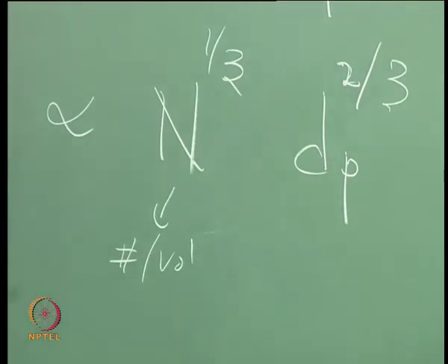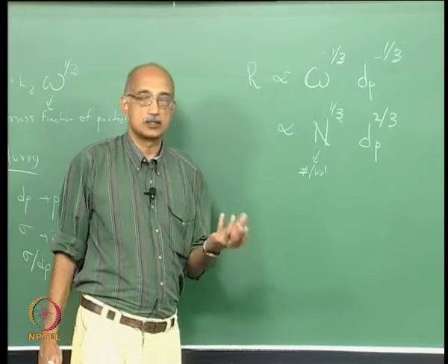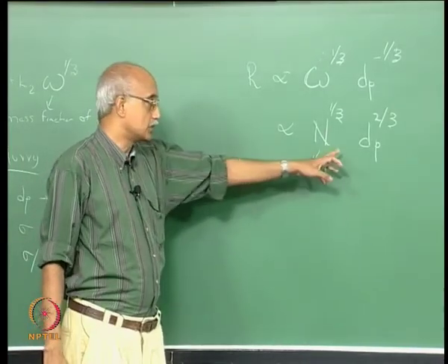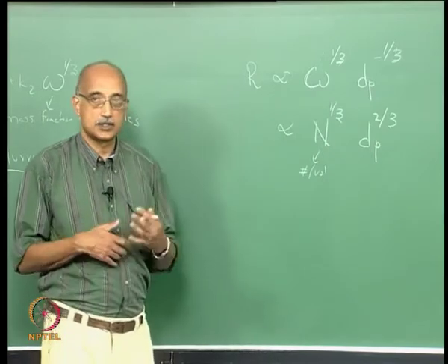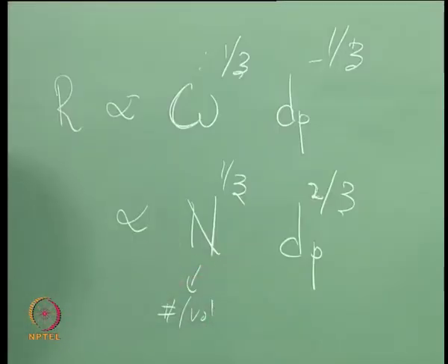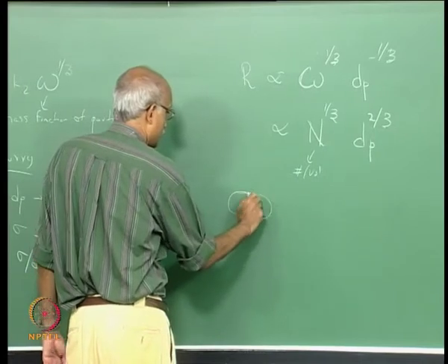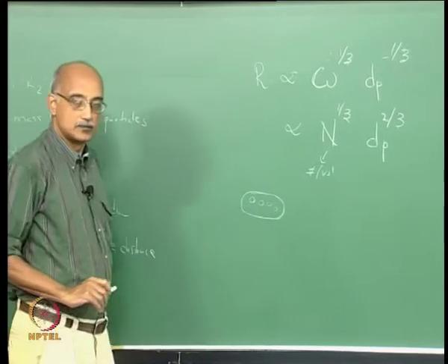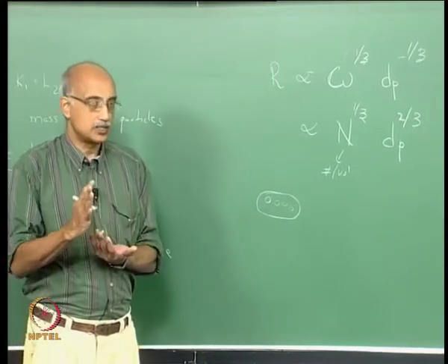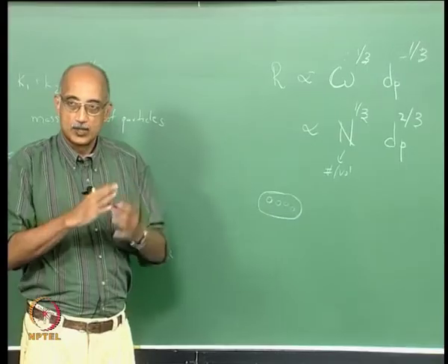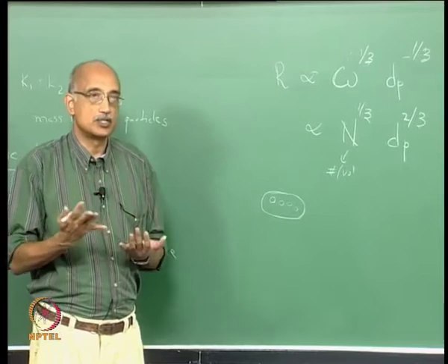So, this is more commonly how the polishing rate is related in terms of number concentration and particle size. This gives a better physical picture that as you increase the number concentration of particles in the slurry, the polishing rate increases, and also as the particle size increases, so does the polishing rate. And the reason that happens is because if you actually look at polishing as a mechanism, you have a surface, a large surface, which is coming in contact with smaller particles, and the polishing is done by the small particles removing material from the larger surface, essentially through an abrasion mechanism.